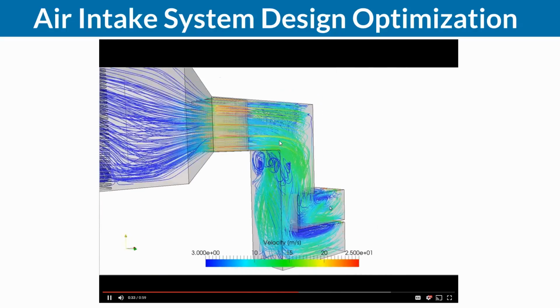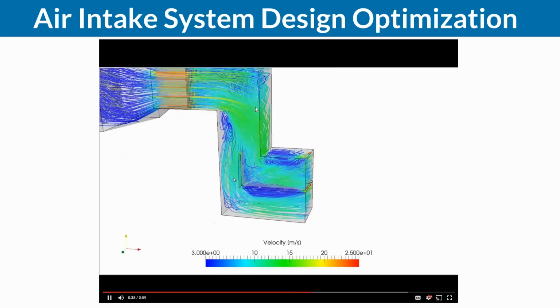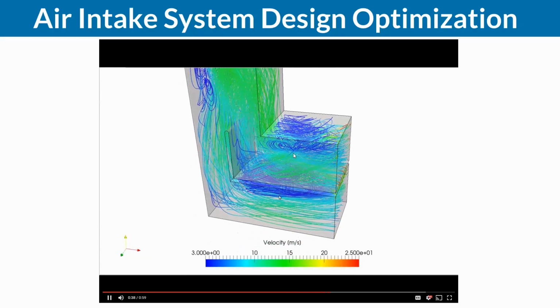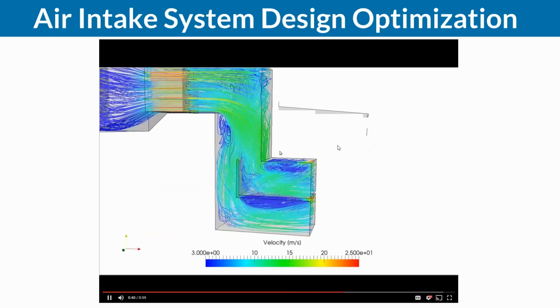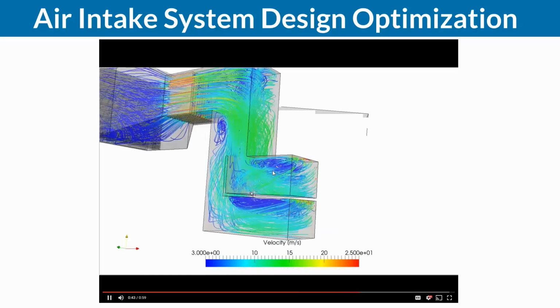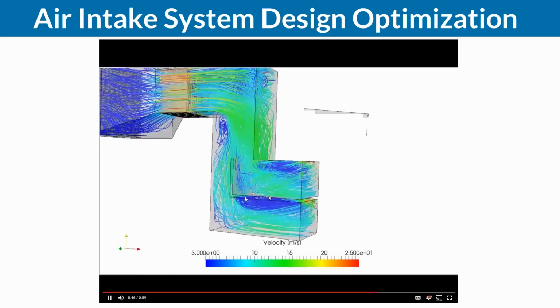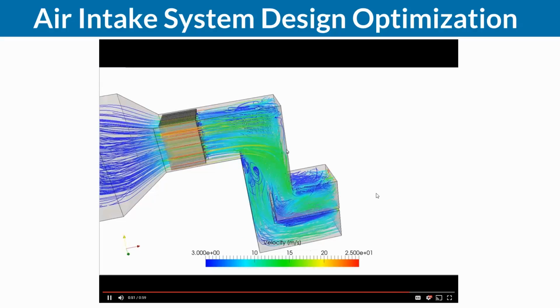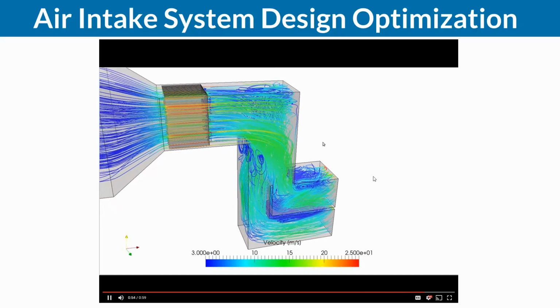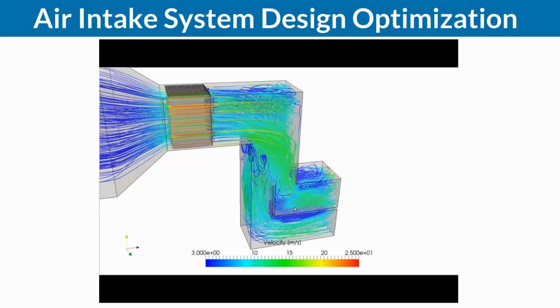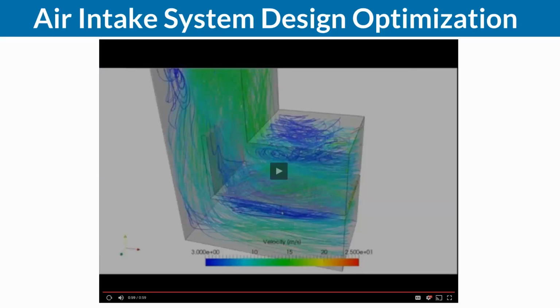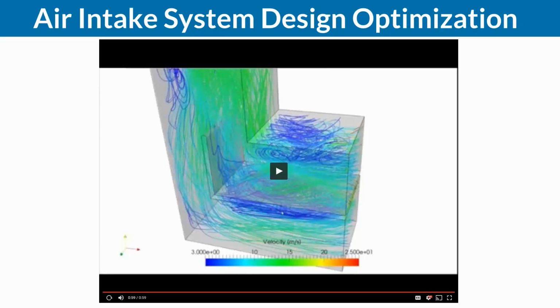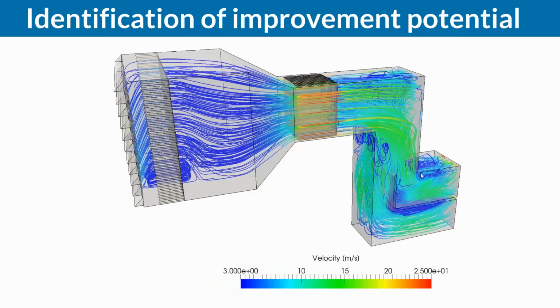Same happens after this 90-degree turn, and then on both ends or outlets of the system, we can see these huge vortices being formed, and a backflow recirculation area appears. And this now fine-grained access to how the flow field looks like allows me as a designer or engineer to make design decisions on how I could improve that, right?